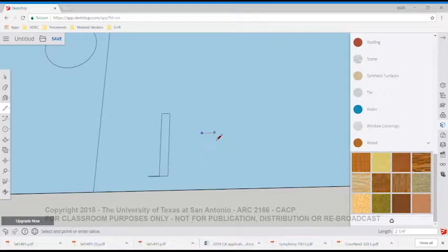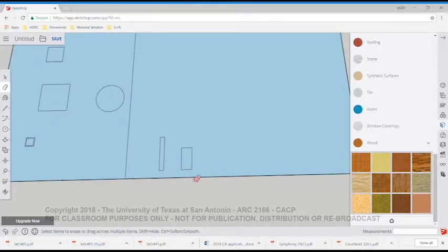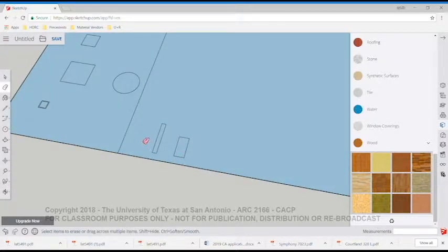I might use a 4 by 8 in wood. And 4 by 8 again isn't actually 4 by 8. It is going to be 7.25 inches deep by 3.5 inches wide, or somewhere around there, depending on the kind of cut, maybe. Just go ahead and clean up some of our tails. But those are primary beam elements, and we're kind of laying the profile flat. We want to build the profile first.